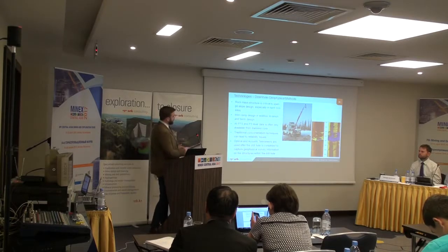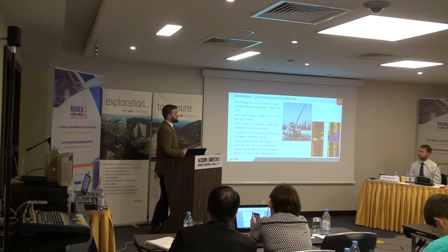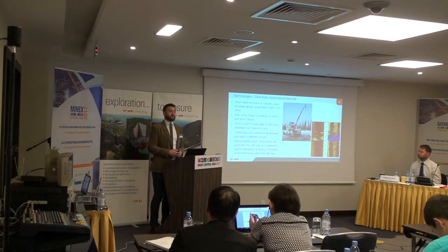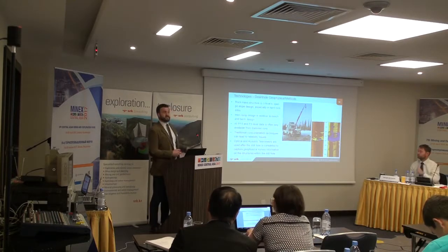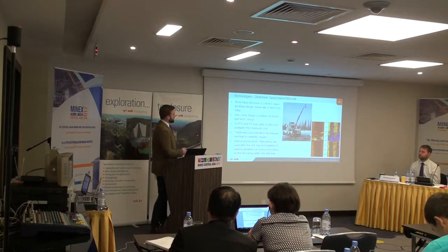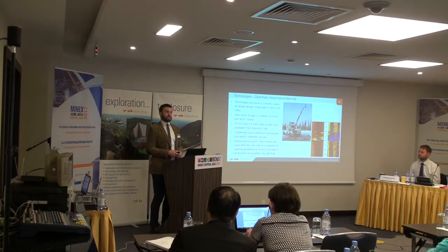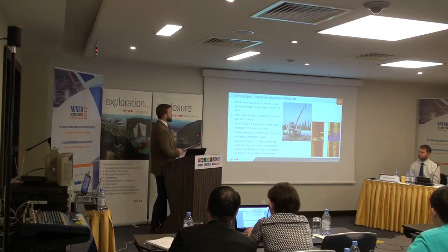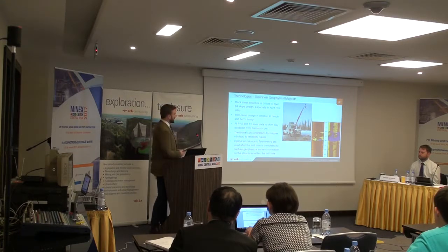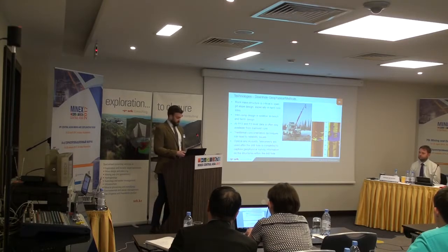I'm just going to flick through them very quickly, so I won't have much time now. The acoustic televiewer is a fantastic bit of software that we've been trying to use more in Kazakhstan. It is used internationally, and it really gives you a good understanding of what the actual rock mass structure is like. You know, we're still working on projects in Kazakhstan where you use the core integrator tool, which has a lot of variability and, more often than not, ends up in a conservative pit slope design. So this is a technology that we would recommend for any of our studies.